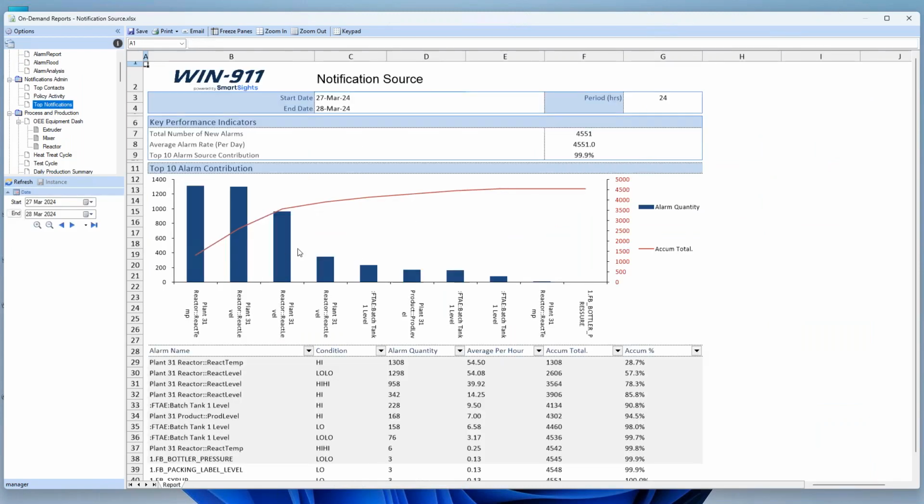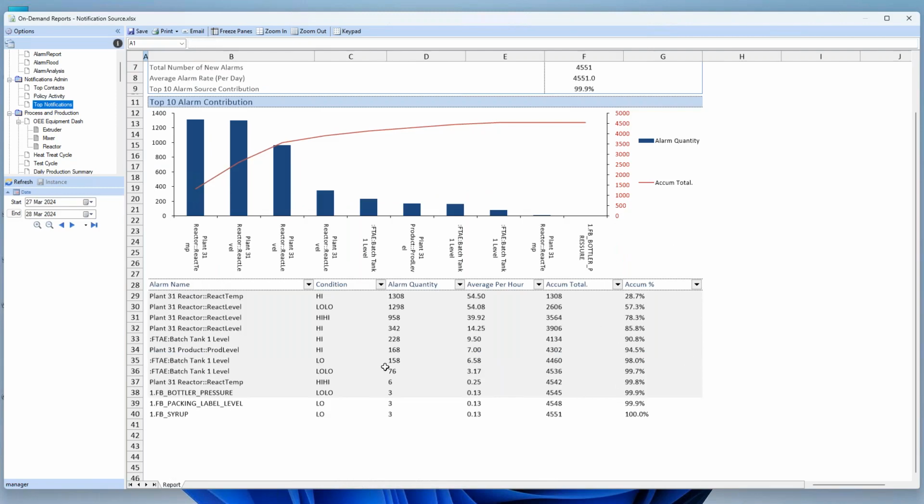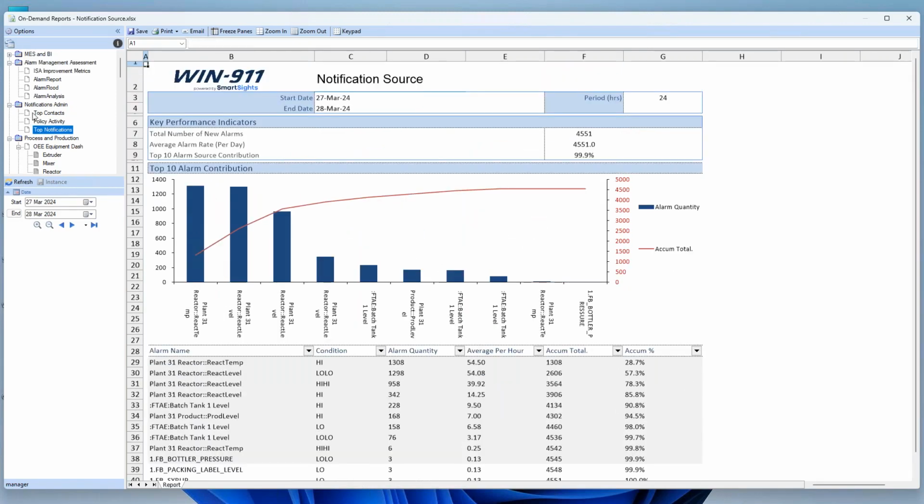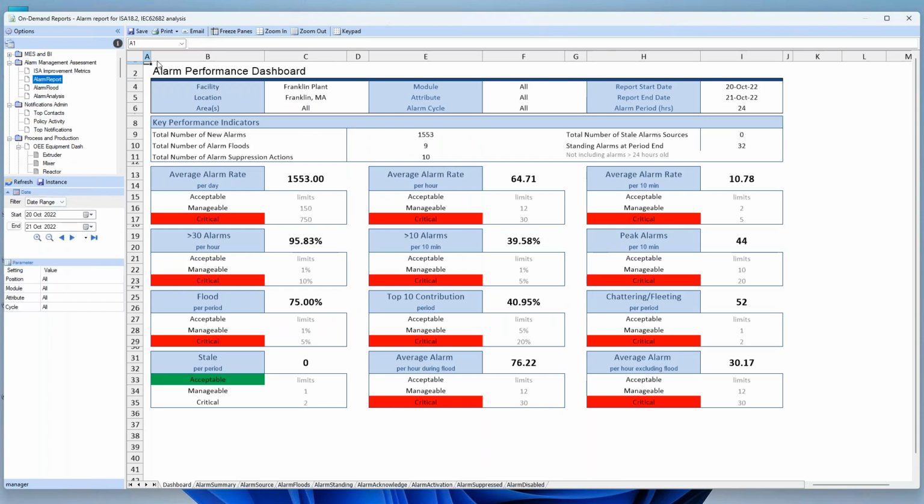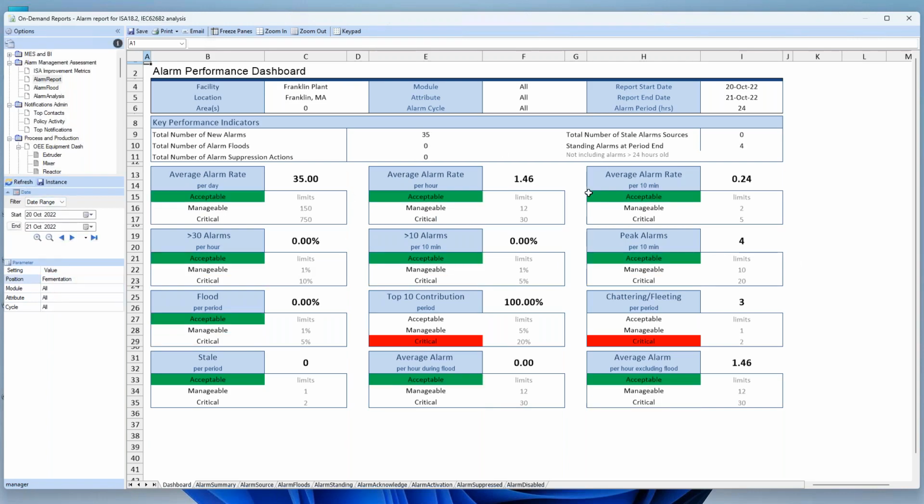We can see how many alarms are happening, right, in different areas, again, using the alarm history. We can look at a dedicated ISA analysis telling us where the good and bad areas are in different time frames or different areas of the plant, for example. Right, so beyond what the iFix HMI or the historian is doing, we can take that data and turn it into meaningful information for process optimization, for compliance, for alarm rationalization, and so on.